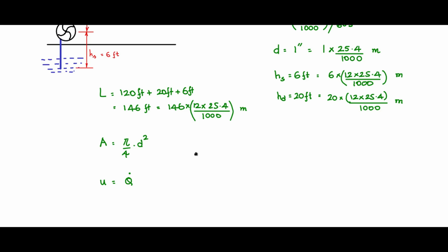This volume of water is flowing through the pipe every second, and that pipe has a cross section area A, and you could divide by that A to obtain meters per second, the velocity of the fluid. So therefore Q dot divided by A, this is meter cube per second, this is meter square, therefore you will get it in meters per second.